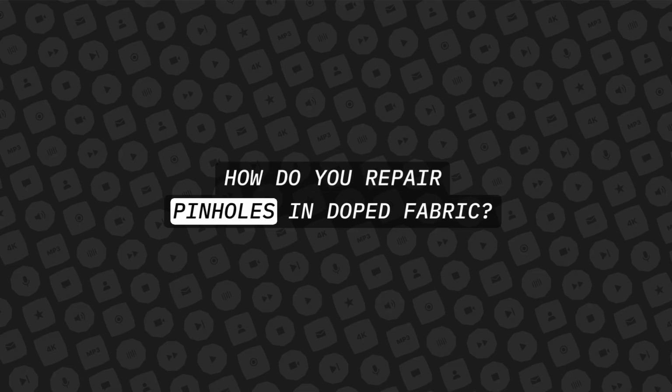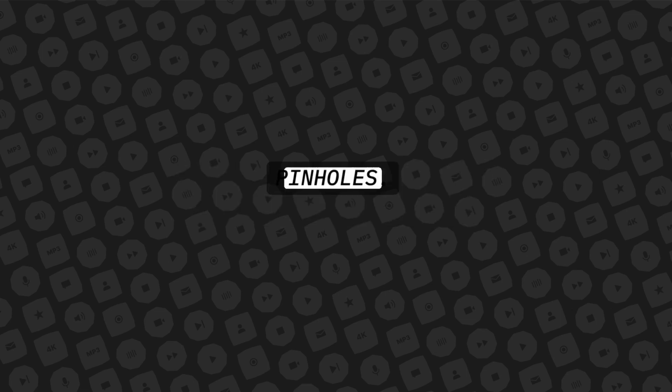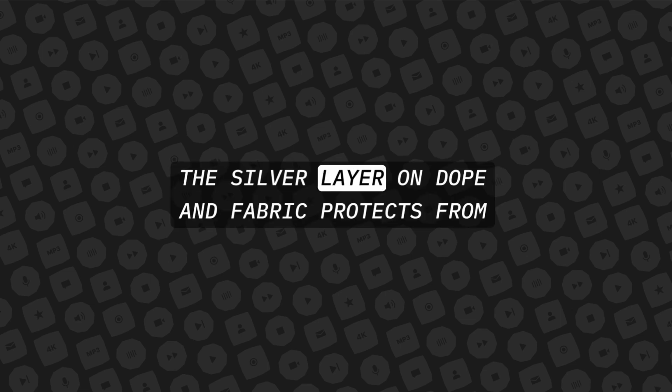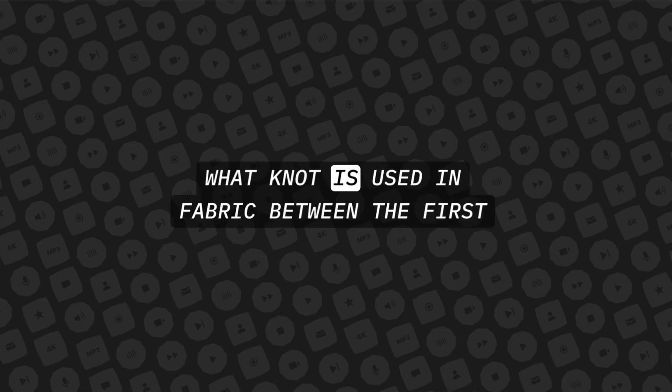What kind of wood is used in aircraft besides solid wood? Plywood or laminate. How do you repair pinholes in doped fabric? You push on the dope with the retarder onto the pinholes. The silver layer on dope and fabric protects from what? Ultraviolet and rot. What knot is used in fabric between the first and last knot?